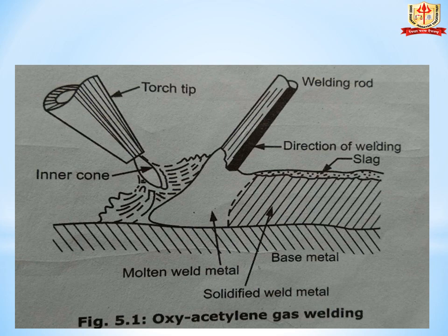The cylinder containing oxygen is painted black from outside and that containing acetylene is painted maroon. Two pressure gauges are fitted, one indicating the gas pressure in the cylinder and the other the reduced outlet pressure. Generally, the working pressure for welding and gas cutting varies from 0.14 to 0.21 bar.